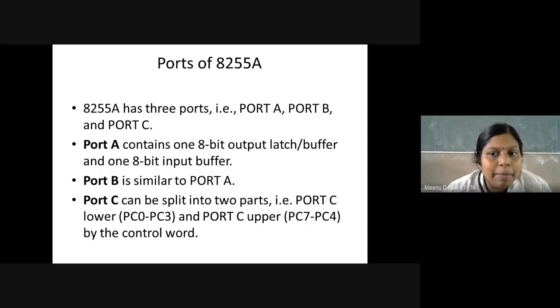Then what is said about port A? It has an 8-bit output latch buffer and one 8-bit input buffer. Latch means the output is latched. Somewhere you are going to see the name latch. What do you mean by latch? Latch means once the output is received in the corresponding register, the output is not going to change even if you change the input.